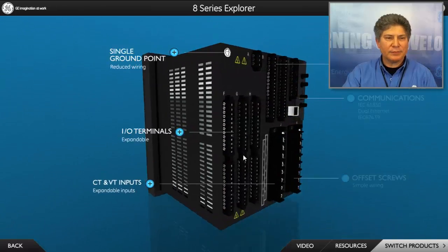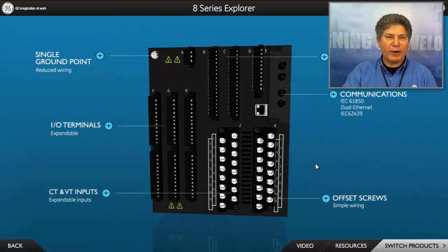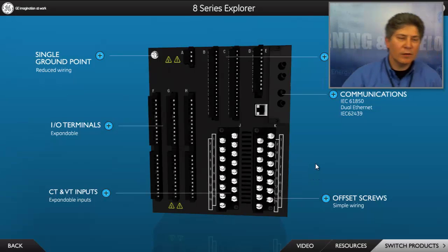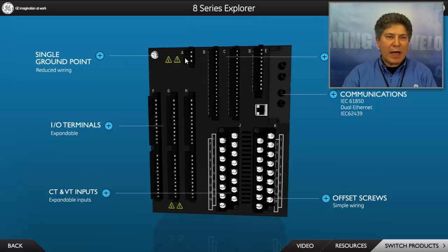Along the back, we have our connections. So here at this point, we have our different connection points. One of them here, this is our main power coming in. We've got our live, neutral, and ground. We've got one single ground connection, as opposed to on the SR relays, where we had the filter ground and the safety ground. We now have one ground only. There's a single chassis ground as well. So everything ties back to the chassis ground point.